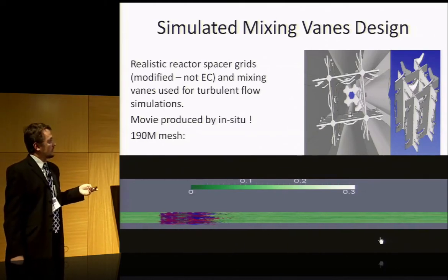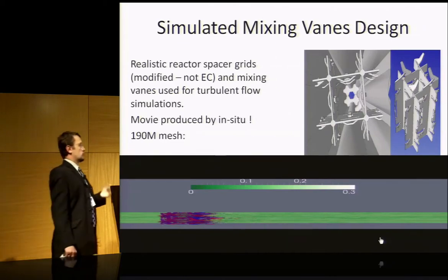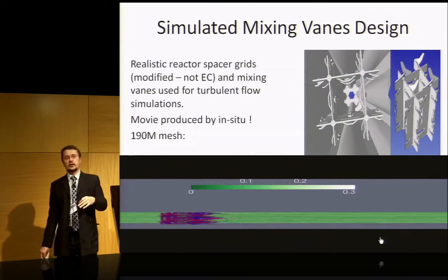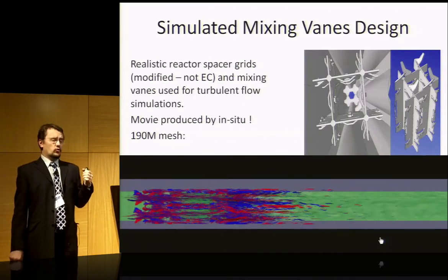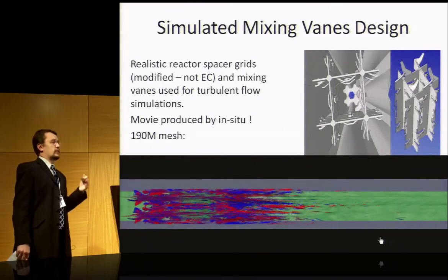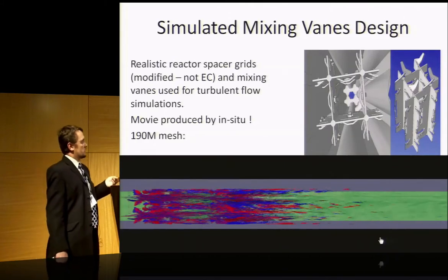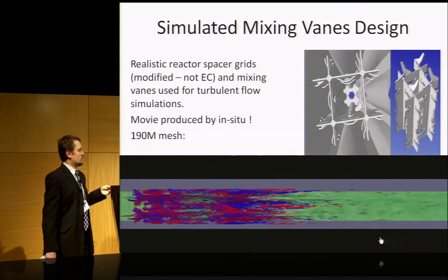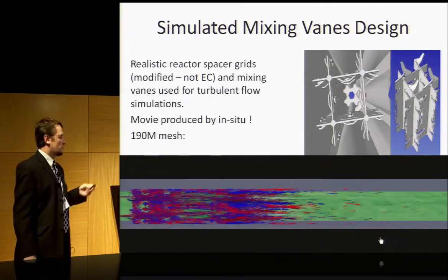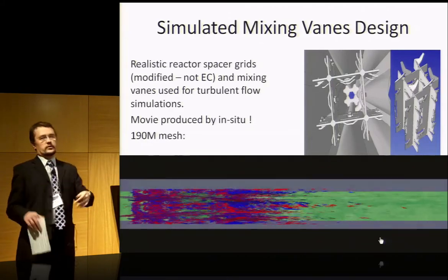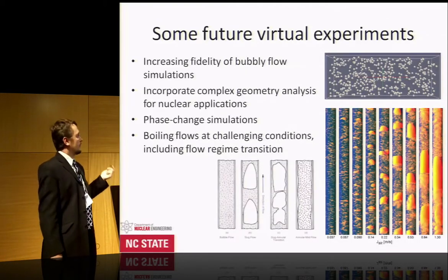Now, this is a very, very low Reynolds number compared to what a reactor experiences. Unfortunately, when you do direct numerical simulation, your mesh requirements go up as a factor of Reynolds to the power of 2.25. If you have to increase it by a factor of about 120 from where we need to be, you have to take 20 and raise it to the power of 2.25. And then there is a time step restriction, so the overall cost is Reynolds to the power of 3.